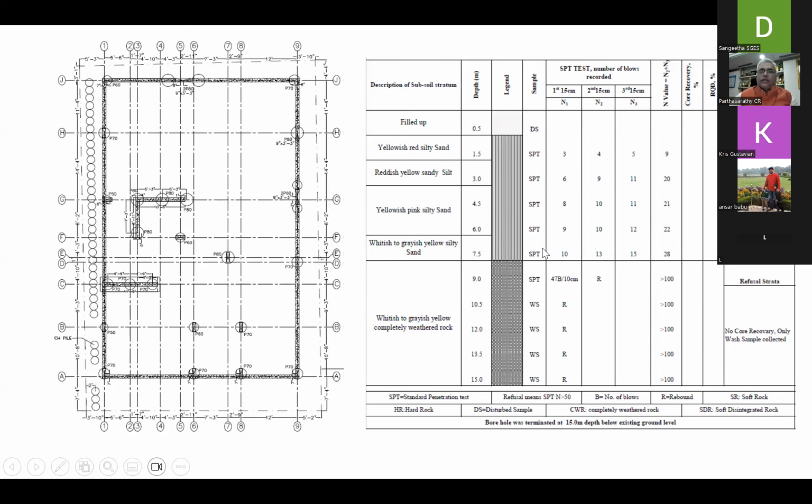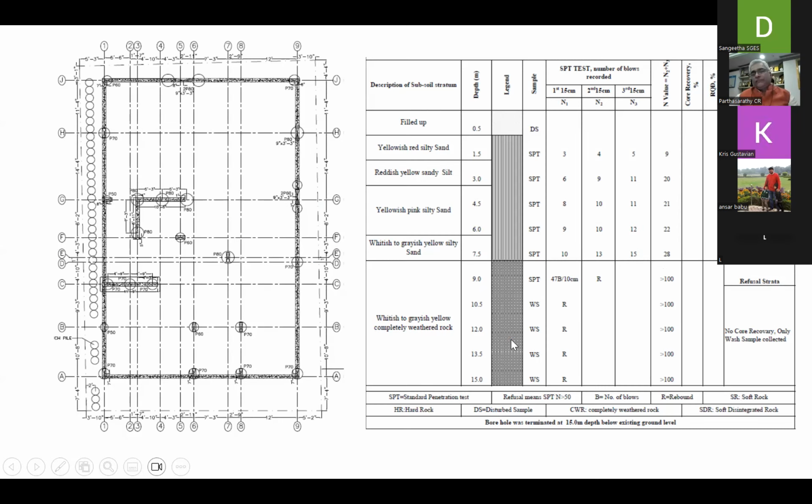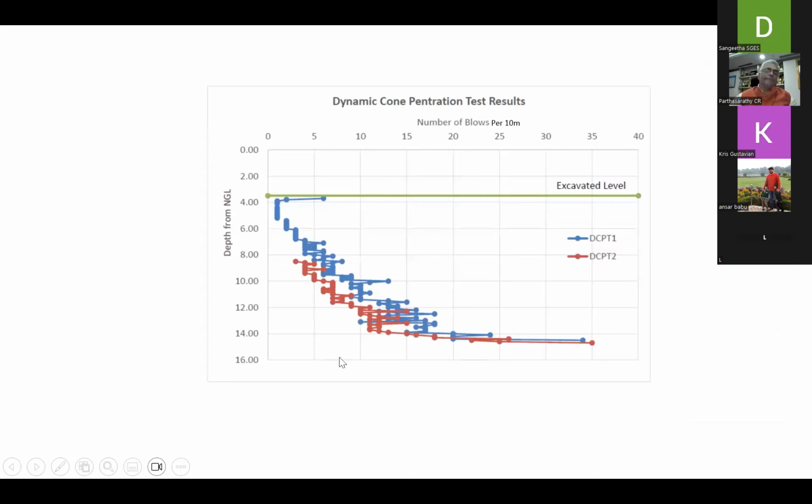When you look at the geotechnical data, the refusal to N values is reported to be around 7 to 8 meters, and that is where they terminated the pile, into the rock where N equals 100. So the termination criteria is very suspicious. I do not know how to evaluate the termination criteria. Say N equals 100, they stop here. So when I actually did the test, the pile failed. So let me show you the result of the pile.